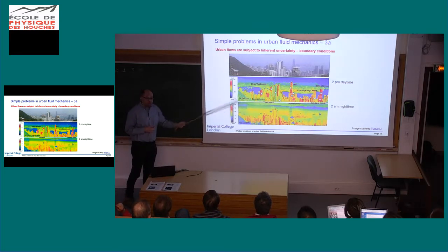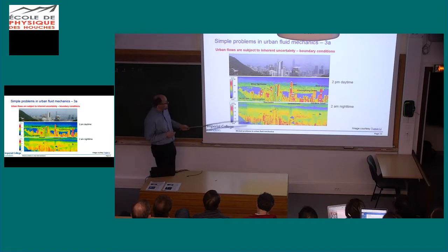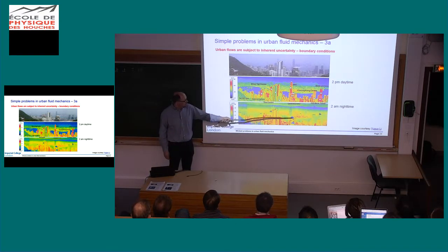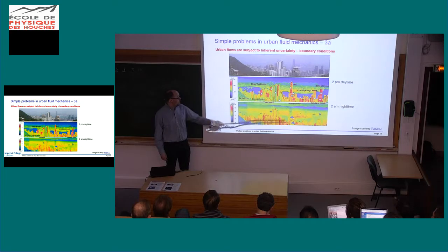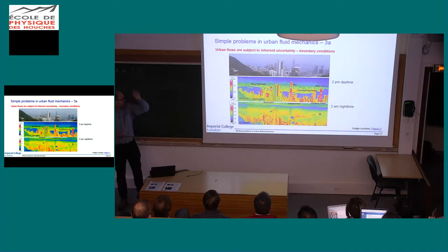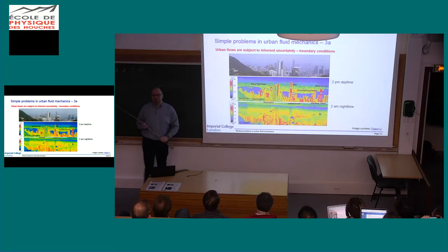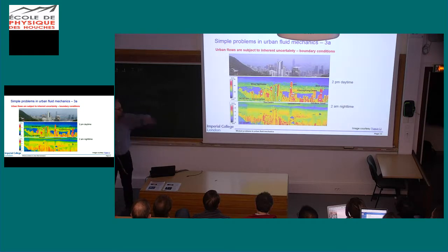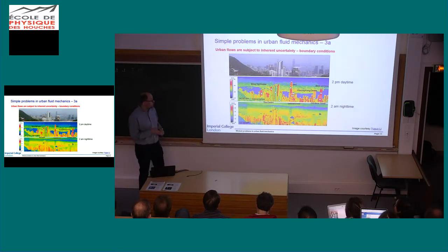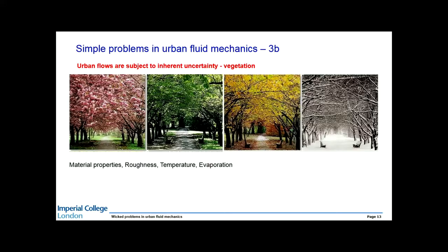This is during the night. So also during the night you see that the city is a lot warmer. One of the effects that is very important here is the concept of radiation trapping. So you see it here beautifully. So these roofs, they look out to the sky. So they're very cold. They're now 10 degrees because they just radiate out their energy freely. But inside the city, the radiation remains trapped. So you just get bouncing back and forth of long wave radiation. You also, of course, have sources. We're going to talk about that in a bit. And that's going to keep the city warm.